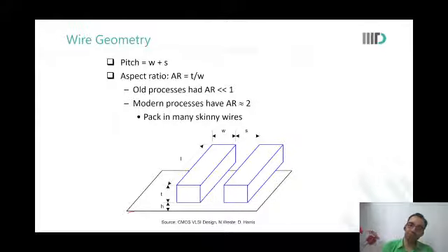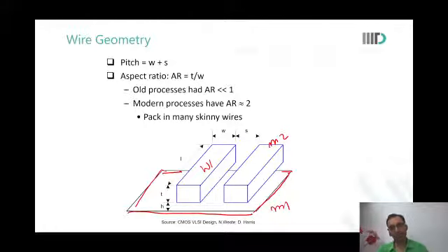So this is a metal running beneath. Let us say this is metal 1 and this is metal 2. What kinds of capacitances will this wire 1 see? It will see a capacitance with the other wire in the same layer, due to the lines of forces.